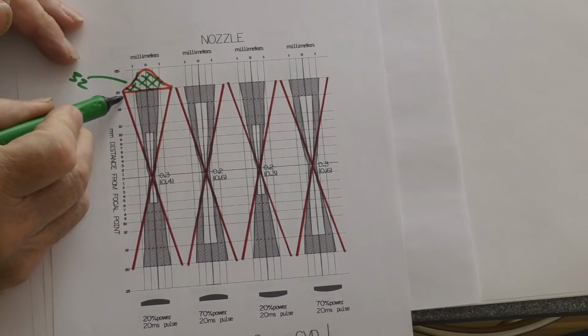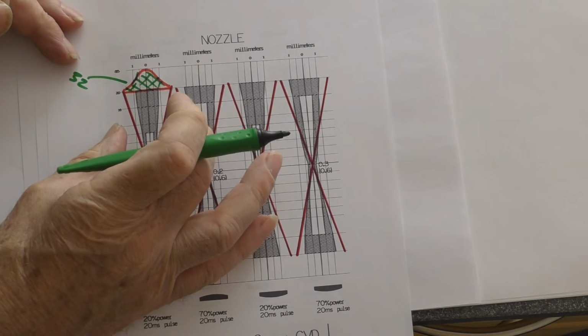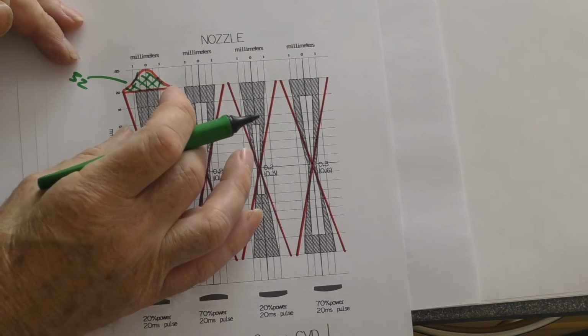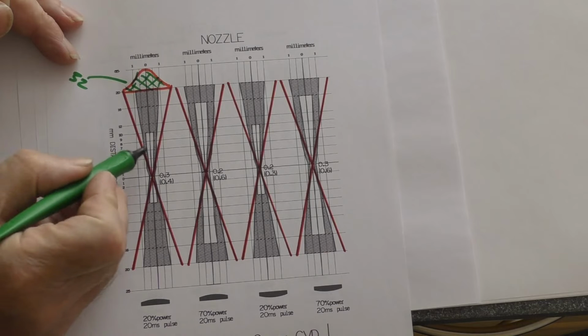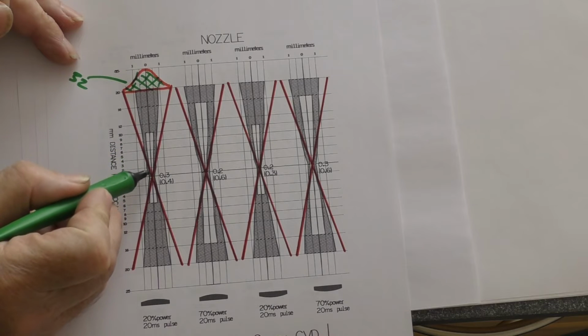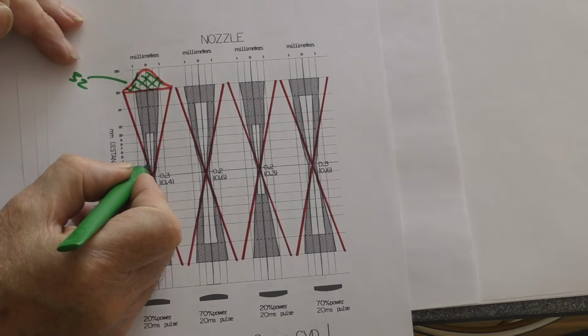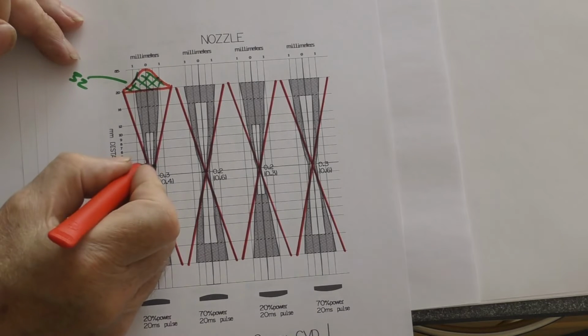But as we start going towards the focal point, the beam starts compressing its dimension. And as it closes in, we've got still 32 watts of power that's being squashed more and more into this same area. And so at this point here, we've still got a normal distribution curve, but that normal distribution curve now looks like this.